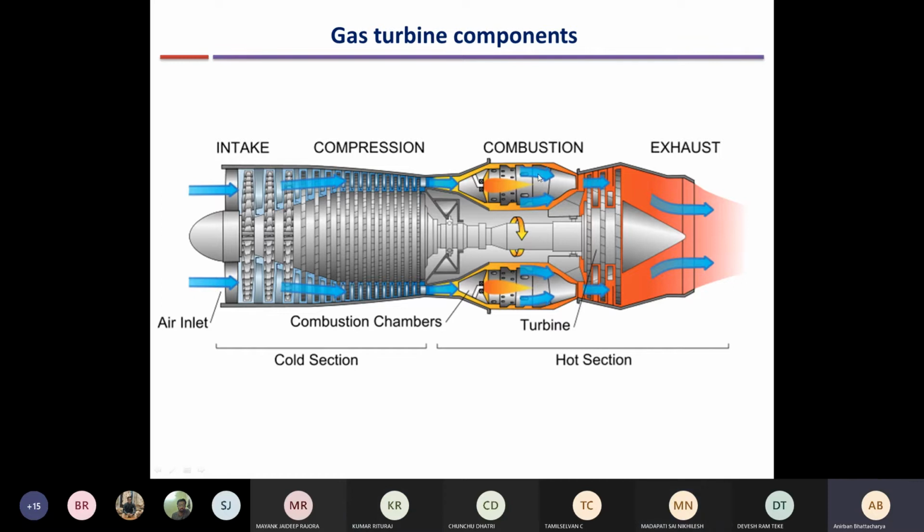That is correct. And to clarify the first answer, if you increase the air, the work output will not increase because your fuel is the same, right? Ultimately the energy is brought by the chemical energy of the fuel. If I inject very little fuel but keep increasing the amount of air, the temperature rise itself will decrease, and the total energy carried by the air fuel mixture will not increase. The volume can increase, but because the specific enthalpy is reduced, we will not get more work output, because work output depends on how much energy is carried by the fuel.